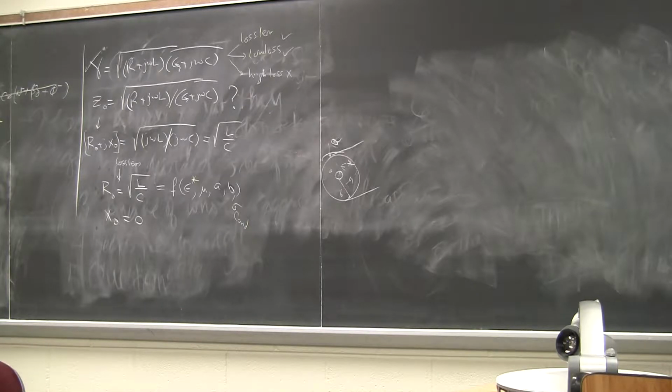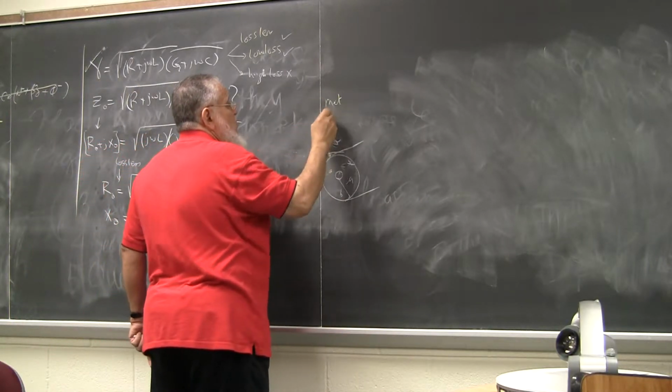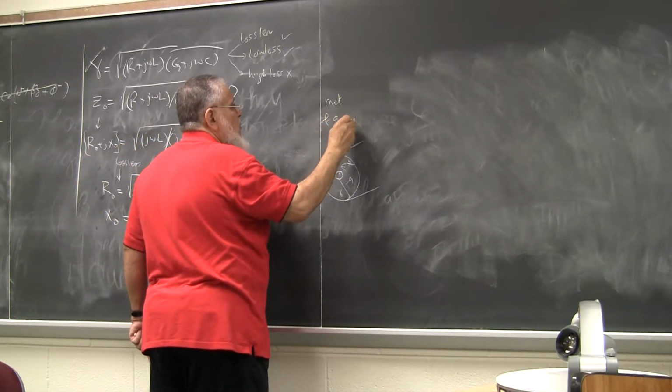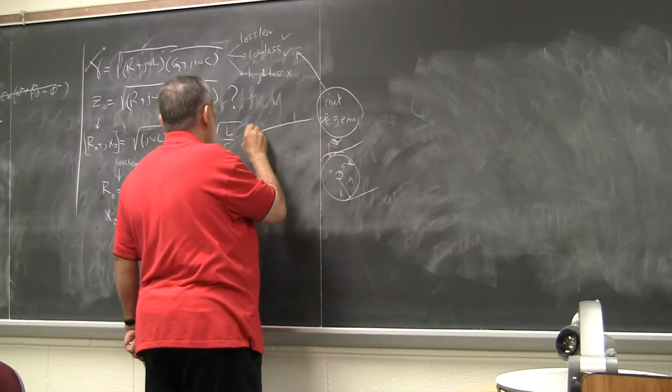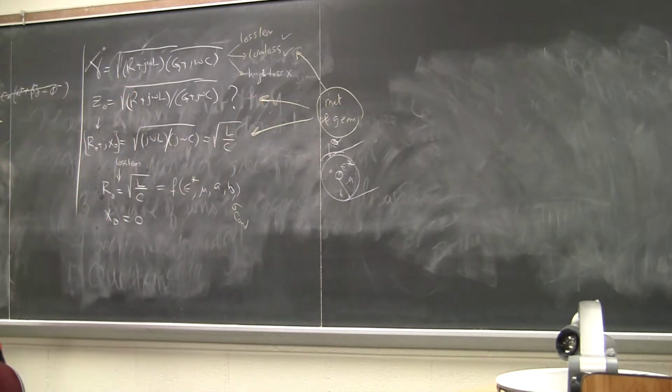In the general case, your Z naught is a function of the material and geometry. Right? That's all material and geometry. And so is gamma, material and geometry. So material properties and geometry will decide for us how much is Z naught, how much is gamma. Okay? So if I have one line, without exciting it with anything, I can tell you how much is Z naught and how much is gamma, because it's a function of all that. Assuming, obviously, we're talking about linear systems.